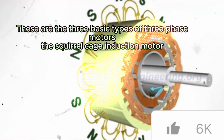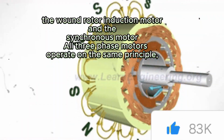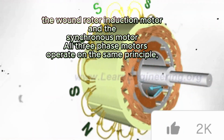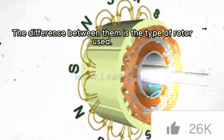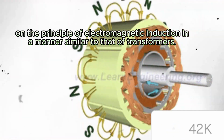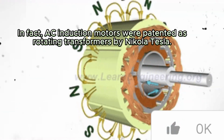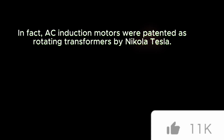These are the three basic types of three-phase motors: the squirrel cage induction motor, the wound rotor induction motor, and the synchronous motor. All three-phase motors operate on the same principle, and they all use the same basic design for the stator windings. The difference between them is the type of rotor used. Two of the three motors are induction motors and operate on the principle of electromagnetic induction in a manner similar to that of transformers. In fact, AC induction motors were patented as rotating transformers by Nikola Tesla.